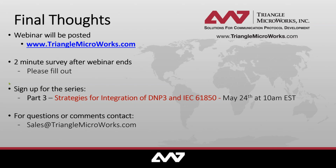And if it's subscribing GOOSE, in addition to having the communication parameters of the GOOSE subscription, it also needs to know the structure of the GOOSE message. And for that, the CID file needs to have additional extracts, at least from the IEDs that are publishing the GOOSE messages that it has to receive, because that's where it finds the data set and as such how the GOOSE message is structured. I hope that clarified.